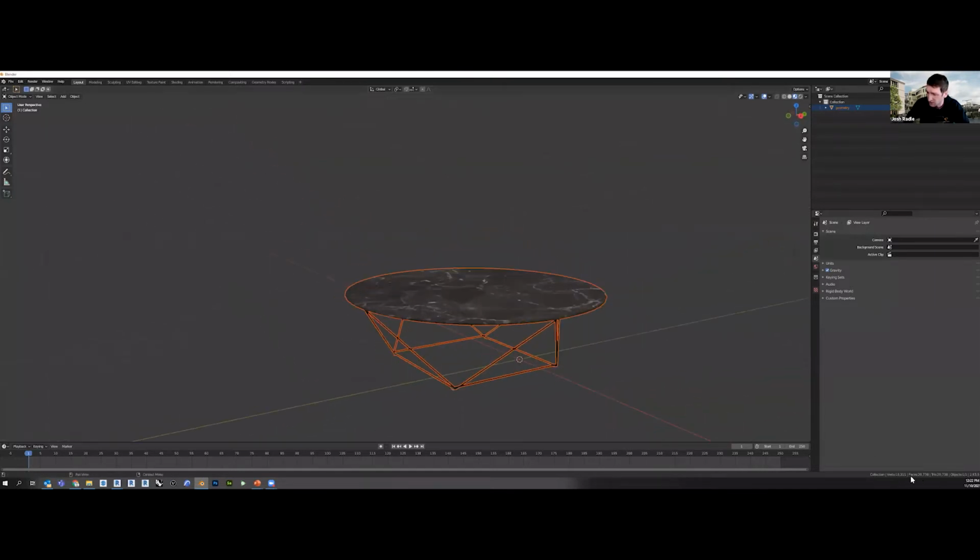But we can see down here where it says these faces. So right now there's 20,738 faces and 20,738 triangles. When we're creating custom Enscape assets, there will be a warning that pops up, like I'll show you guys when we import this one, where it says there's a warning of over 20,000 triangles. So that's one thing to have in the back of your head when you're creating these custom Enscape assets. It's just for performance reasons.